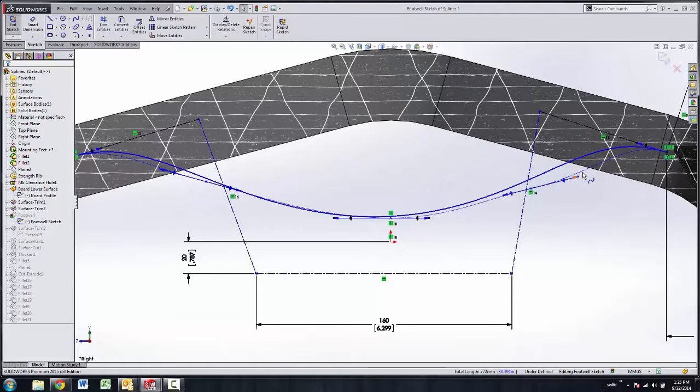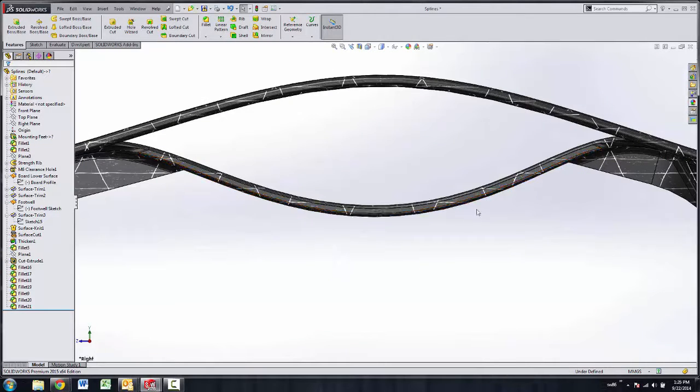It's turned this into the section line, but more importantly, it's taken all the children that this feature was a parent of and switched them over in the database and added them to this line. So when I go and leave this sketch now with this new spline controlling it, you can see it's nice and smooth here. I won't get any parent-child conflicts or errors over in the menu. And you can see this has got quite a few parent-child relationships in the menu as I go through this.